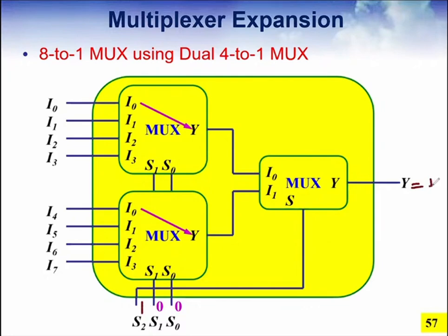At this time, we will be getting I4, as per the concept of the mux. So see the logic: when you make it 1, this line is going to be connected here, and this will block here and will not go further. What will go is this, then it will go here, and this is the connection. So I will be getting here I4.